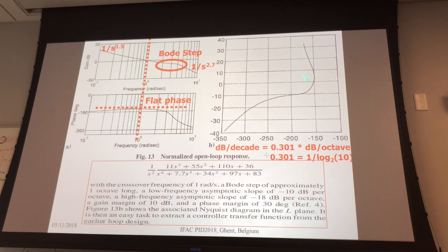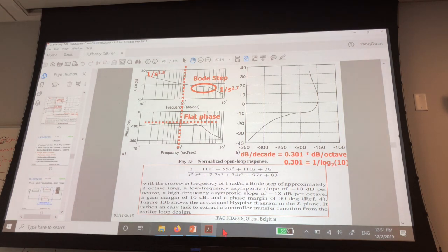There is a period of time in here where this is vertical. When this is vertical, it's an iso-damping property. That means your step response overshoot will stay constant, will not increase or decrease. So with that, it's time to tell you the secret ingredient.